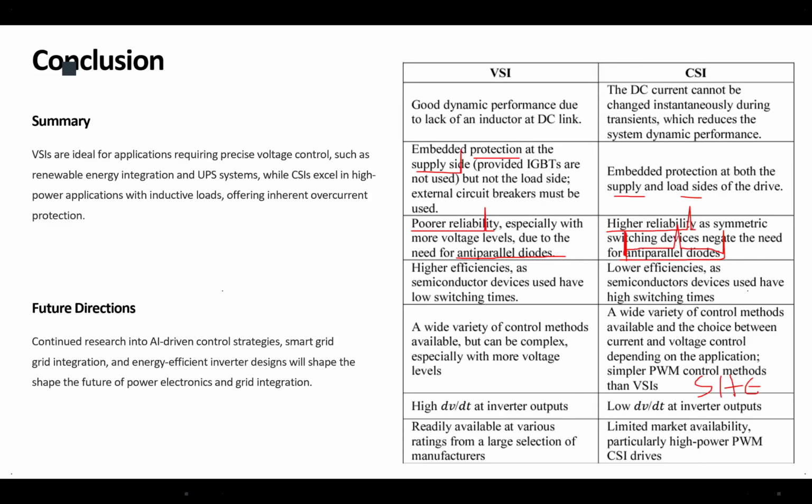When you have a motor and you connect it to a source, at the first step the source would see a short circuit, because the load is not energized. So there is a huge load, and by huge load I mean huge current draining from the source. That huge current drain means, in the time domain, very high di/dt.